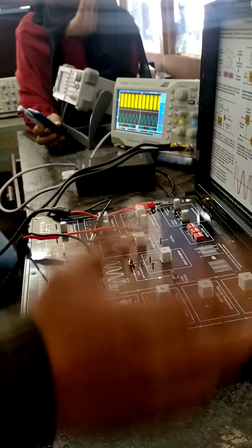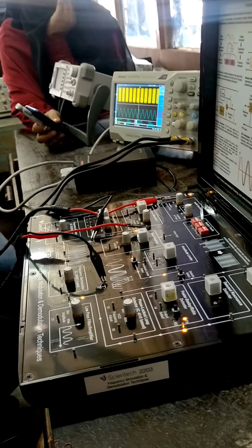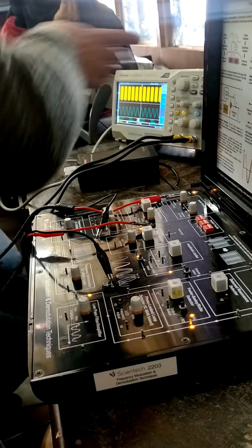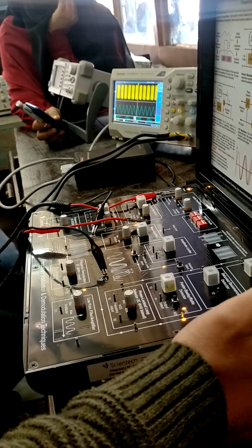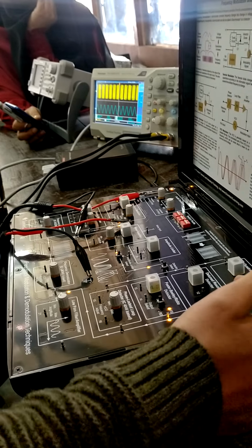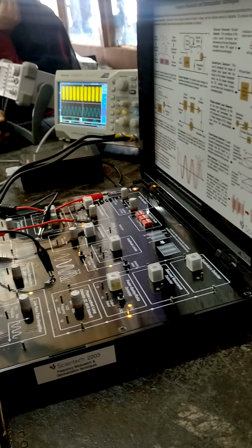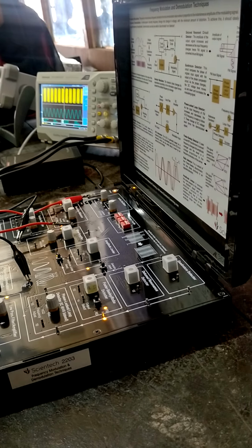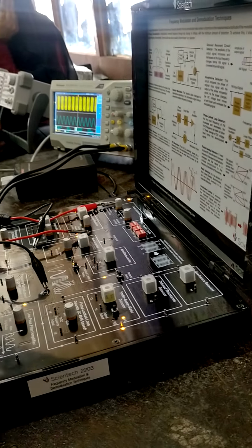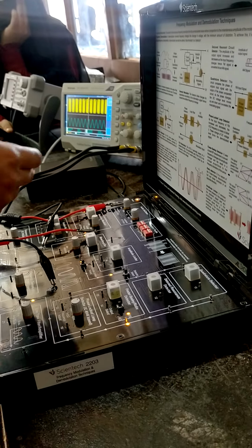Now here also there are various types of detectors. I told you there is also a tuned radio frequency receiver for AM detection. Similarly, there are various types of detectors here also. There is a quadrature detector, a detuned resonant circuit detector, a Foster-Seeley detector, and a phase lock detector. After those detector circuits, there is obviously a low pass filter.